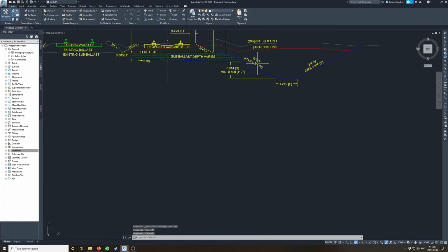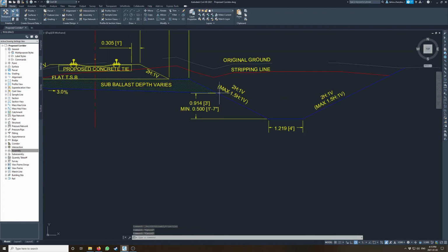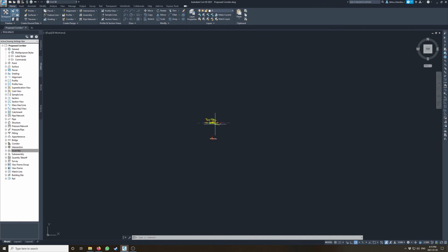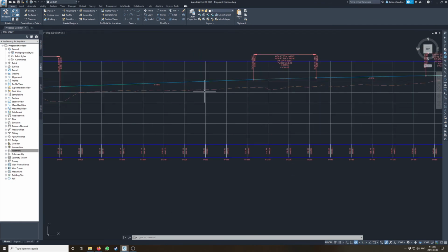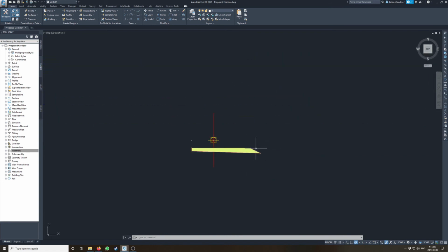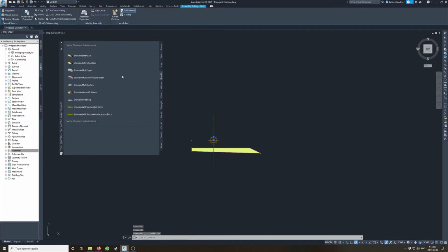Next up, we want to model our ditch. What we're going to do for the ditch is create another profile for the ditch, so we want to reference that profile. For this task, we will go back to our trusty generic links, and we will use offset and elevation, I think. No, slope to elevation. Yeah, because then we can use a 2-to-1 slope and we will link to the ditch.